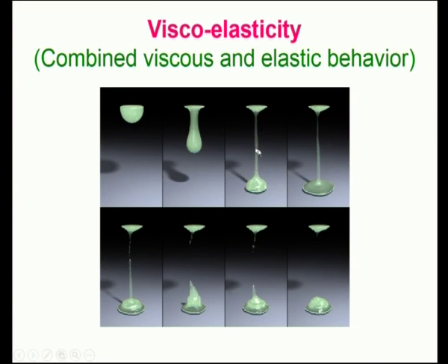Because of this weight, it will try to reach the bottom surface. If you look into the thickness of this, now you are going to give some more time. That is what we call relaxation. Now this is stress relaxation. Now you could see the thickness of this fluid is getting reduced. It is getting reduced further until it ruptures. So finally it will reach a state like this. Or in other words, the gravity tends to release the stress. As a result, the material will start flowing. So this viscous and elastic behavior is typical of polymeric melts.